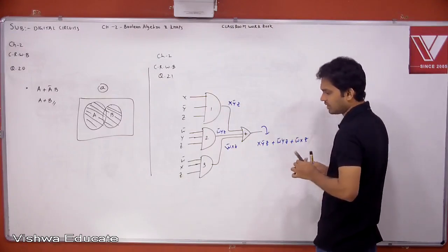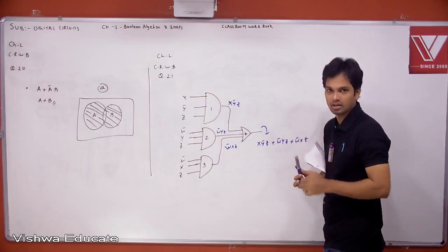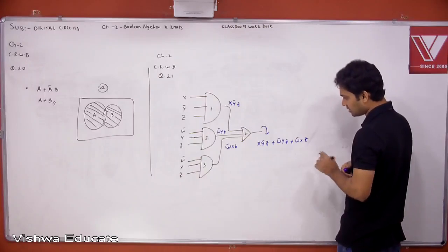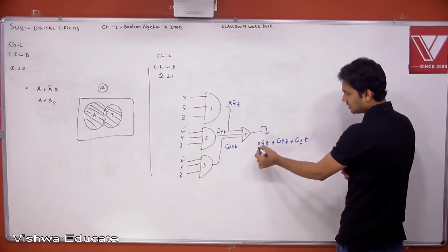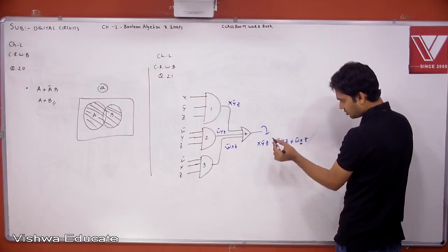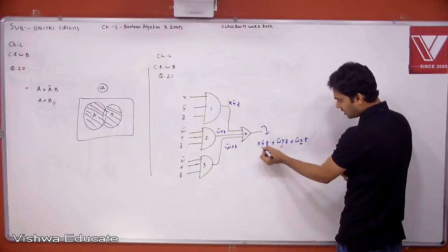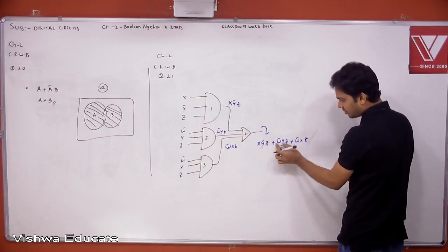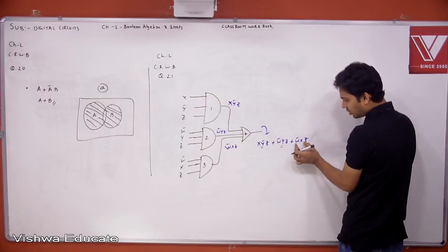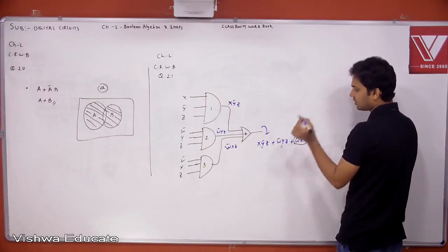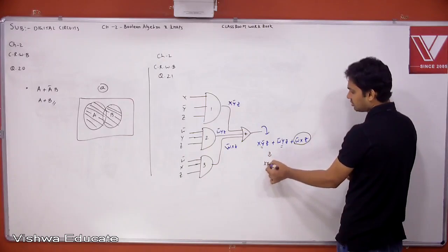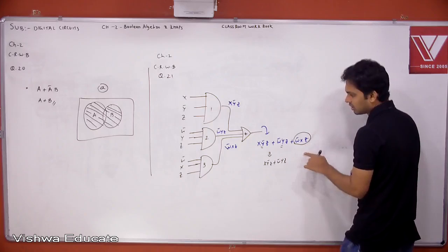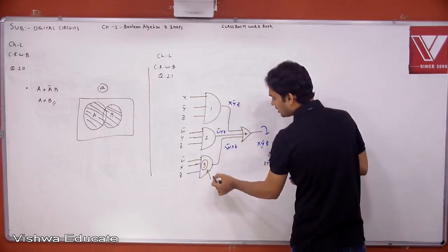Now here one way is to draw the K-map and find the redundant, one method. Another way is find, is there any consensus law here? Yes, x is present. Here also x only. Here y is present, here y bar is present. And the remaining product, w bar z, is here, xz. You can neglect. So what is the answer? X y bar z plus w bar yz. So w bar xz can be neglected. Gate number 3 is the redundant gate.